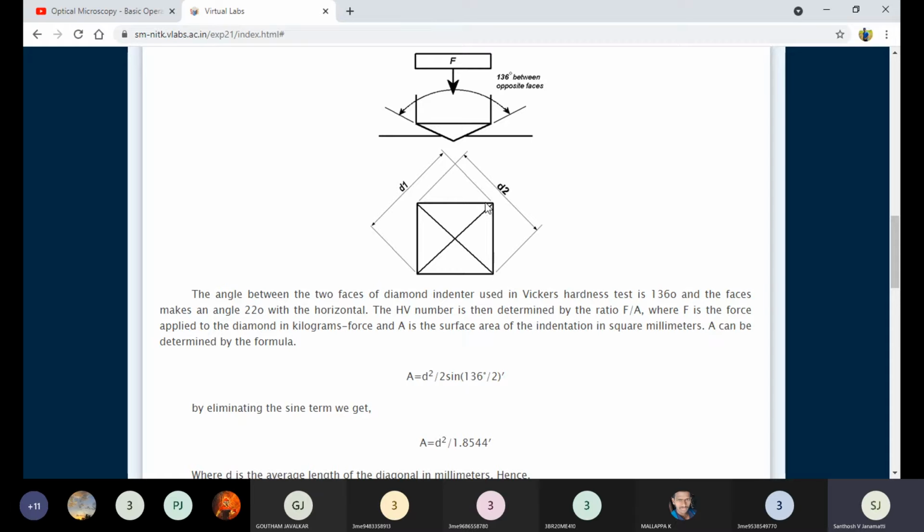Definitely you know very well about the diagonal length of a square. Why is it a square? Because it is a rhombus diamond shape. Whenever we look at that tip in the front view or top view, it looks like a square. Hence the square tip will penetrate the workpiece, and we will get a square shaped penetration over the workpiece. Now we need to determine the diameter of this rhombus or square. Hence, as this is not circular, we cannot.